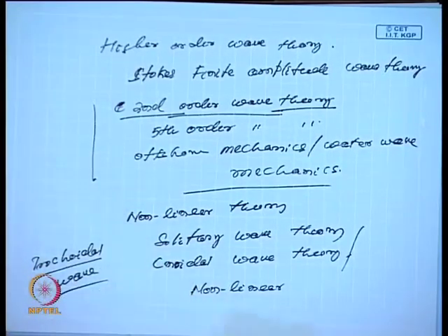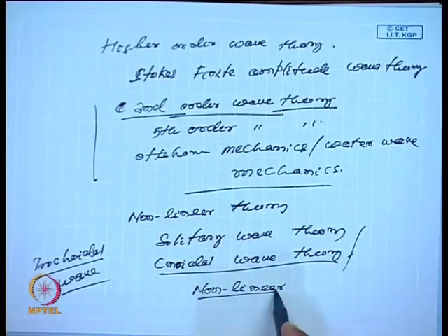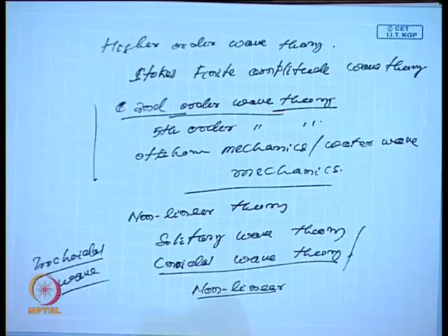In fact, for a large class of problems, there are a lot of results from these theories, but very few problems of a practical nature are handled based on them. Major analyses, whether coastal engineering or offshore engineering applications, most of the time depend on potential flow theory. The viscous effects in potential wave theory, particularly diffraction theory, are almost negligible and are neglected because the structural size is always assumed to be large.